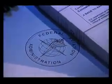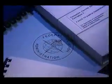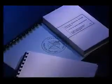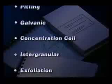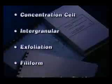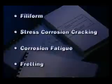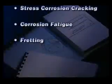There are many types of corrosion that can affect your aircraft. They are described in detail in Corrosion 1, but quickly they are uniform, pitting, galvanic, concentration cell, intergranular, exfoliation, filiform, stress corrosion cracking, corrosion fatigue, and fretting.